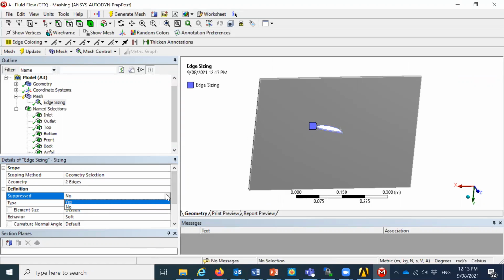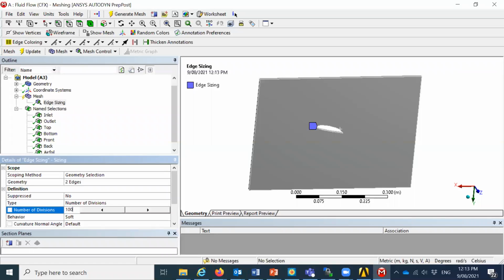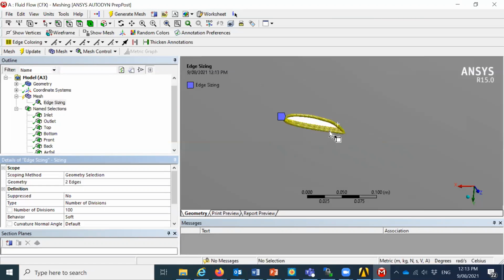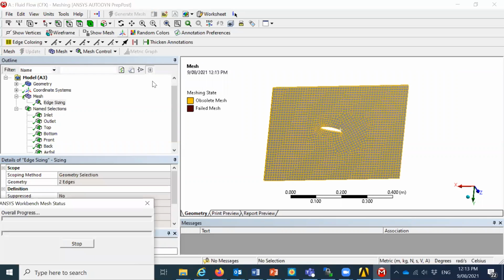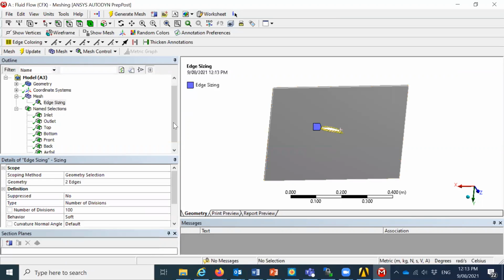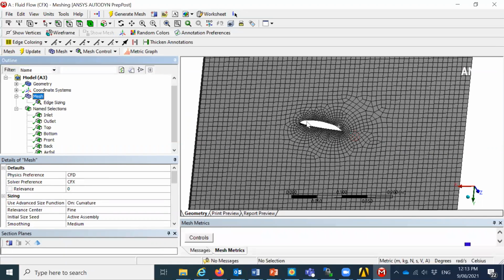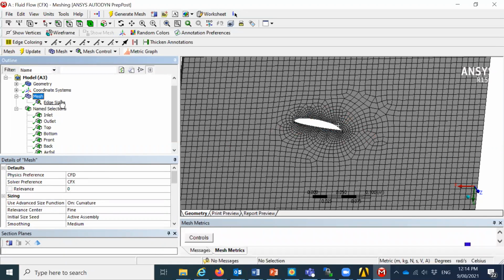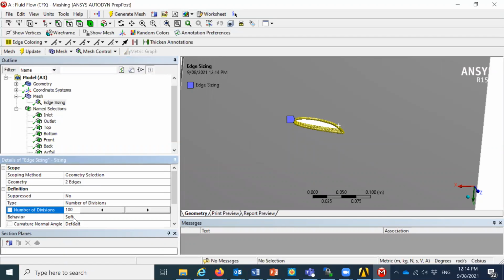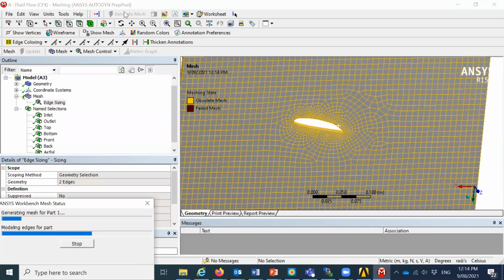Now the surface method is all selected, it is just as it is now. For the element size, we have different options. So I can use number of subdivisions. Instead of, we have now just one subdivision. If I put, let's say, 100 subdivisions, then you see it creates 100 small subdivisions. And if I click on generate mesh, then you will see now we'll get more fine mesh. You look here, we get more fine mesh. Now if I click here, I can increase this number. Let's say I can put it as 5,500 and click on generate mesh, and then see how it looks like.